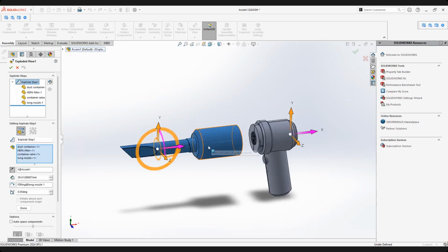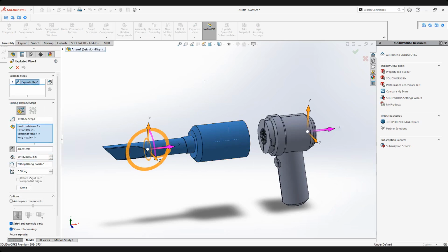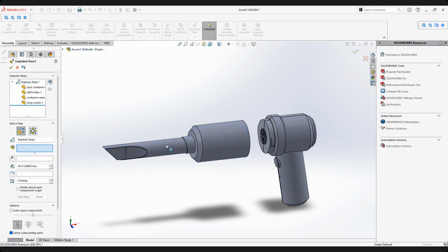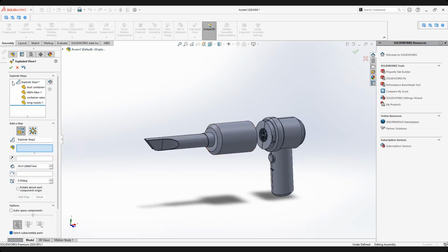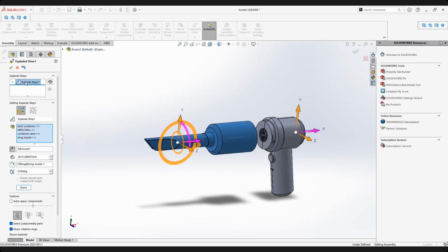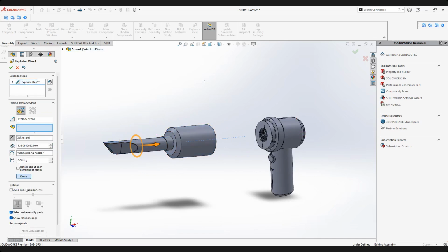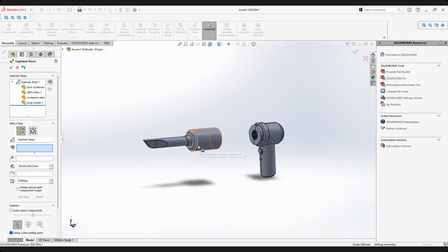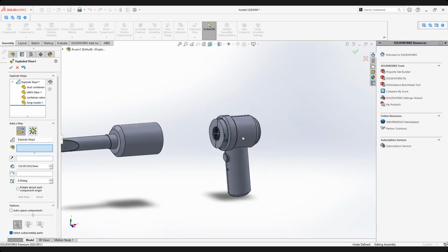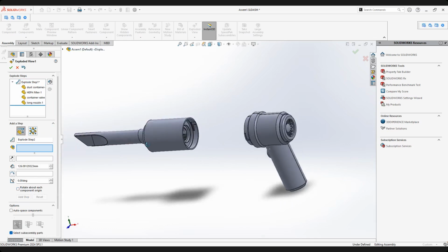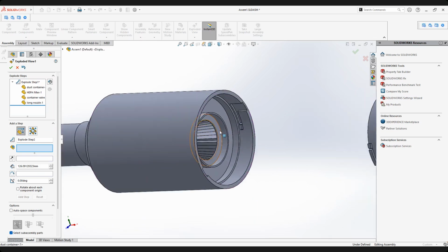Okay, I already did the first setting. So what will be recorded as explode step 1 is done, right? I must click done. So it asks for explode step 2. What will be explode step 2? Okay, I want to adjust again. Explode step 1, I want to adjust. I select explode step 1, I drag it, I make it further like this. Okay, then I must click done whatever. Then it asks for explode step 2. Then what? After we have dismantled this, will I dismantle the front casing? Or I dismantle this group first? This one first.